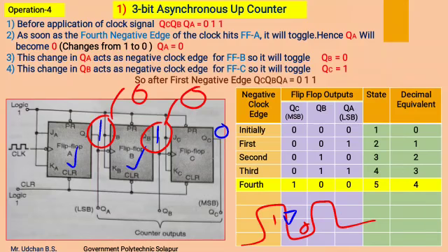the QB changing from 1 to 0, means flip-flop C also gets a negative edge of the clock pulse, as a 1 to 0 transition consists of a negative edge, falling edge. Therefore the output of flip-flop C will also get toggled, means it will now become a 1 which was previously 0.